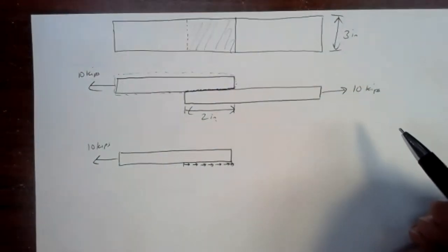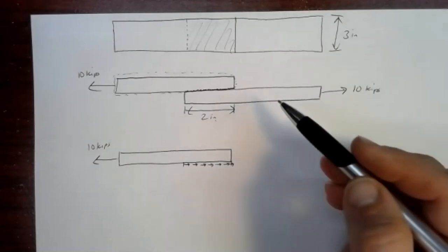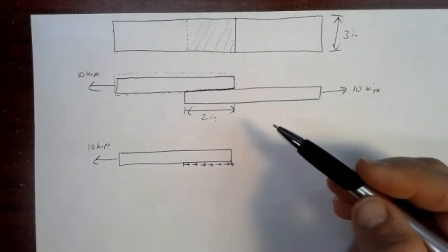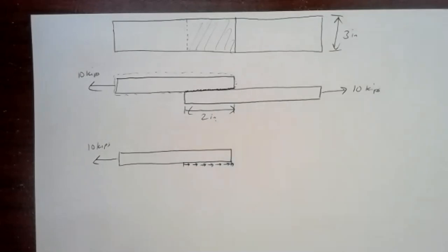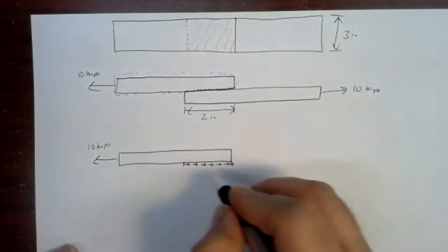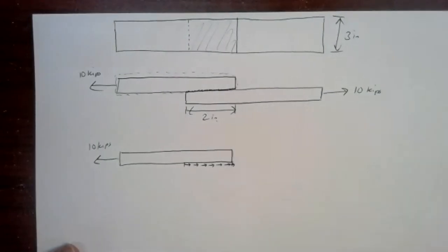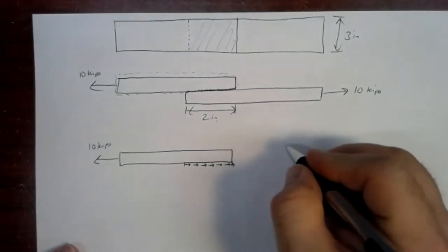I don't know if you've done wood structures yet, but when we do things like scarf joints, we have to be very careful about how we spread that glue. You can't just run a bead of glue down the middle and sandwich the two pieces together. You've got to spread it out nice and evenly, so we have that force spread out over a larger area to lower the stresses.